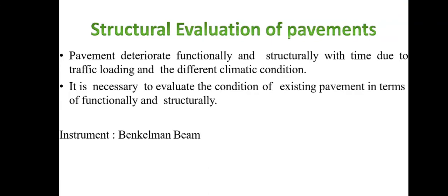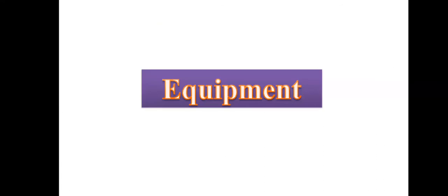Evaluation of pavements, that is structural evaluation of pavements. Pavements deteriorate functionally and structurally with time due to traffic loading and different climatic conditions. It is necessary to evaluate the condition of existing pavement in terms of function and structure. Instrument used is Benkelman beam. Equipment.